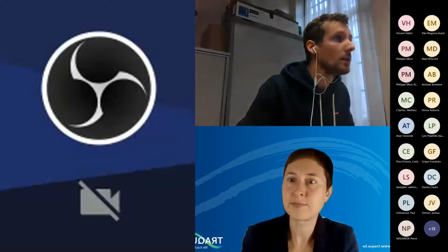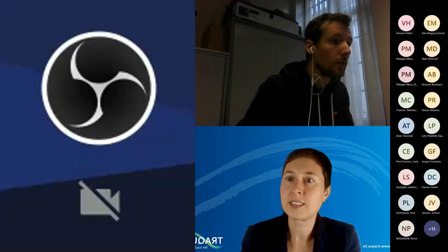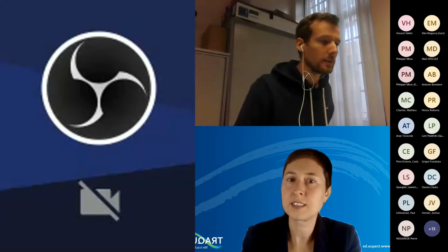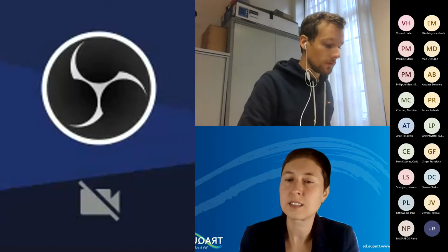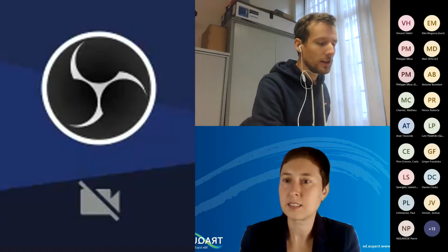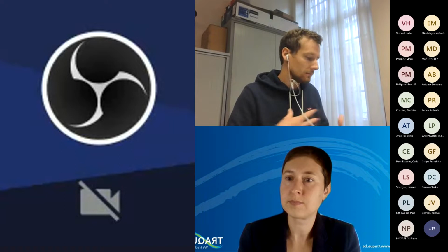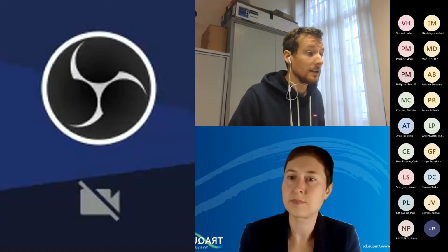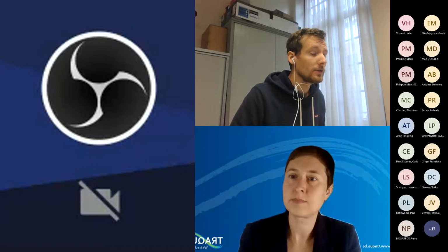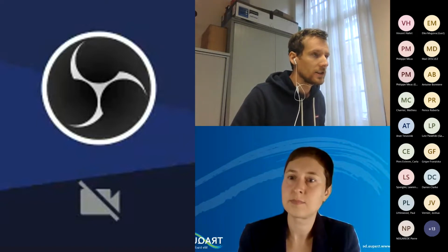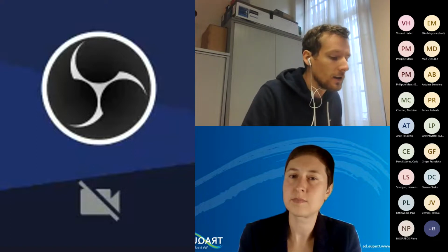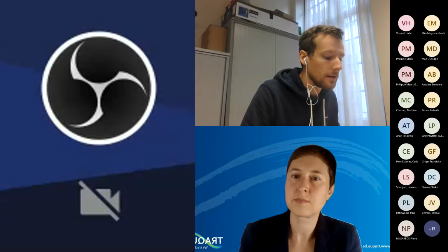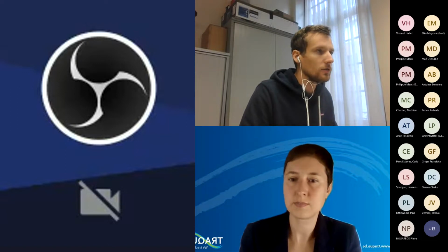Yes, I don't know if it is for Romain. You can apply a lot of different kinds of models to fit artificial breakthrough curves to your field data, and to evaluate hydrodynamic parameters such as coefficients for advection and dispersion, to fit, for example, the longitudinal dispersion, porosity to your field data.